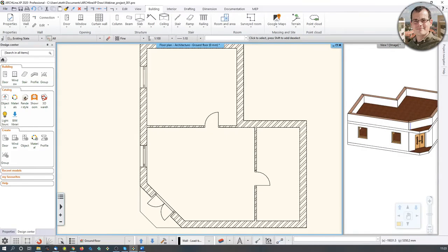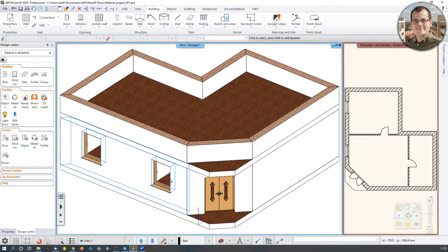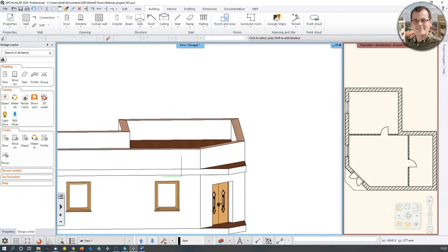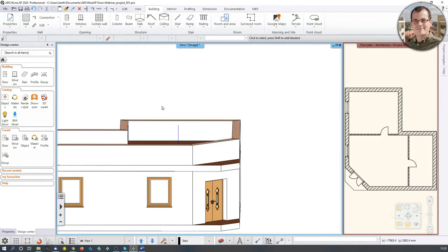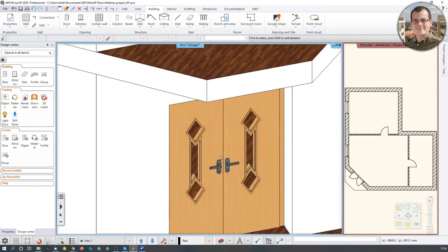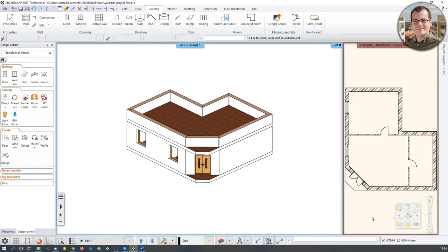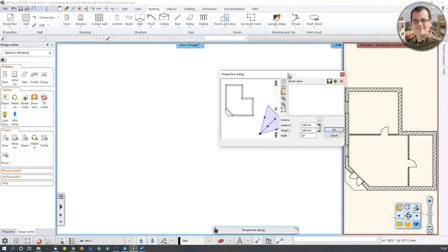Next thing we have to take care of is actually the perspectives. I did talk about this before, but a quick refresher is in order. What we are working on now is something which we call an axonometric view, which means that no matter how far you are looking at things from, the distances would not get shorter like it would normally when you look at something. If you zoom in, you cannot enter the location. No matter how far you are zooming in, you would never be able to enter this. For that, we have a different representation mode, and that is called the perspectives, which can be reached with this eye.